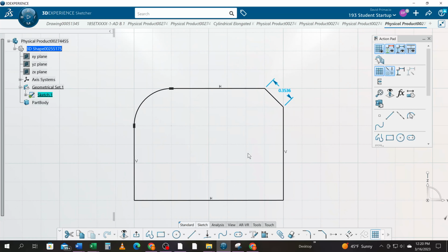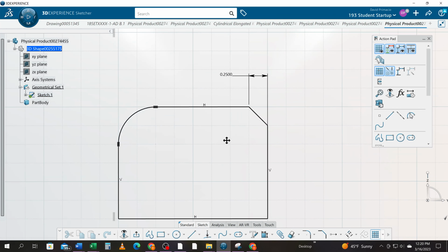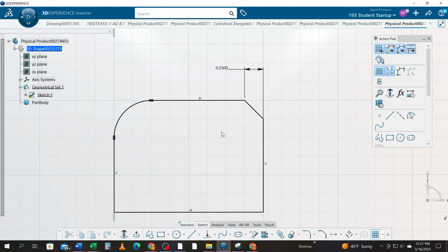What you want to do is tell the shop, you're going to have that raw material, and I want you to measure over from this edge to this point. I want you to measure over ¼ inch and then lop it off at a 45-degree angle. So if you've ever used a chop saw, the chop saw automatically locks it at most common angles, like 15, 30, 45, 60. Okay, it'll lock in at those angles.